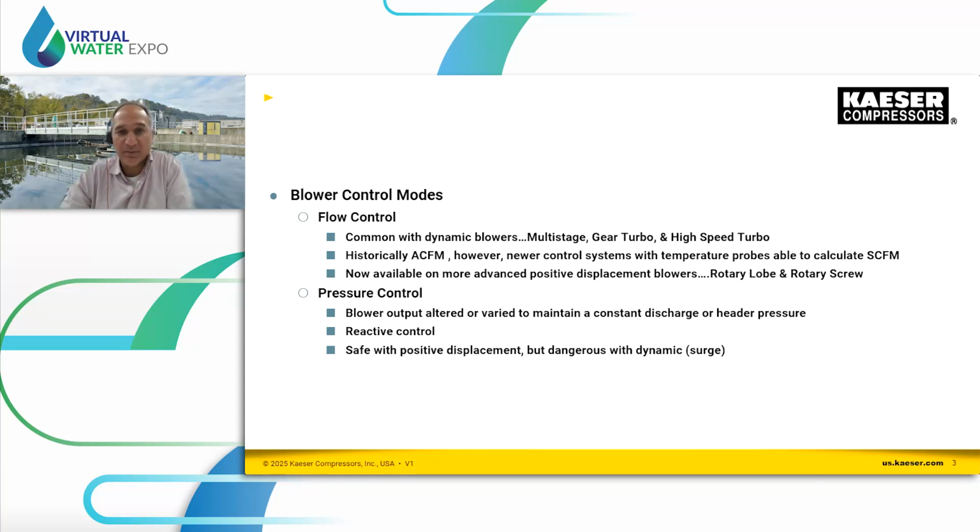If you had a positive displacement machine and you throttled back, you would start building pressure. It wouldn't automatically modulate itself, and it could blow a relief valve or kill the blower. Or if you had something like a weighted loaded relief valve, it would vent off that air. But in positive displacement, this has always been a way to increase your pressure, which then increases your power consumption.